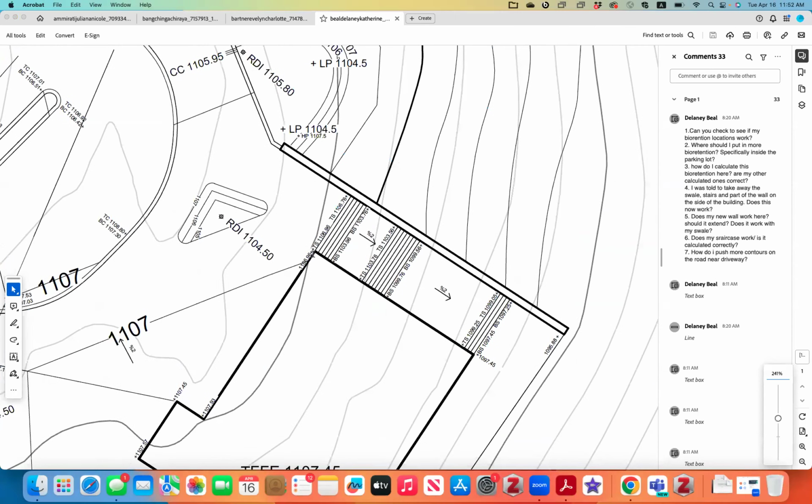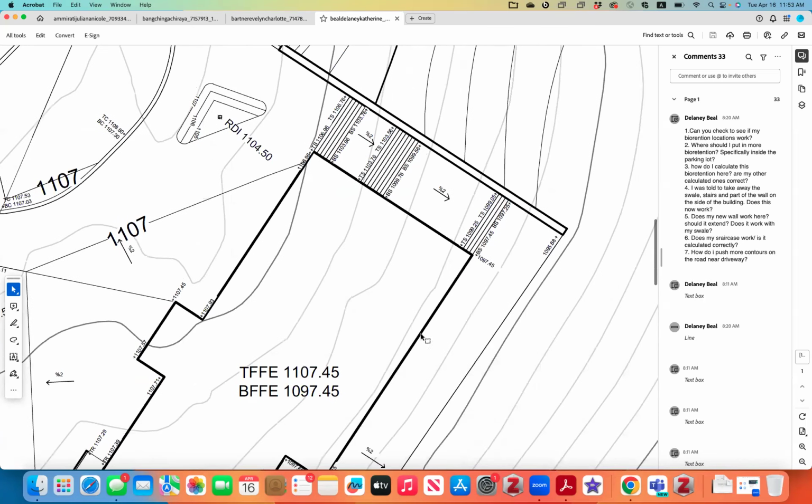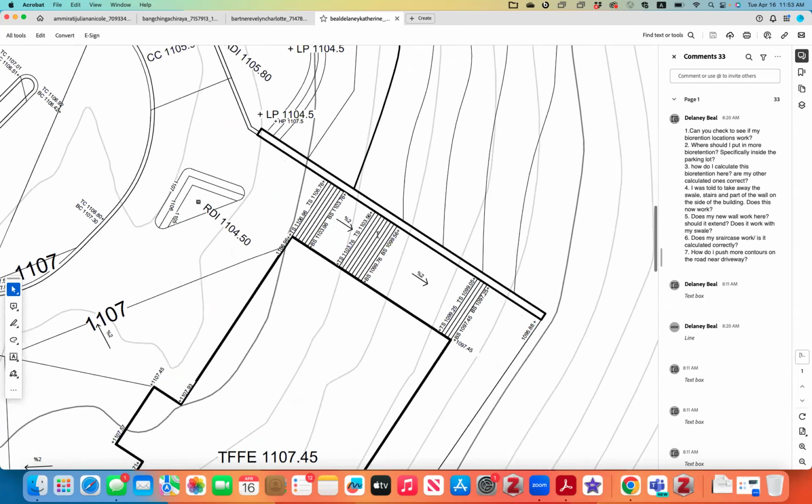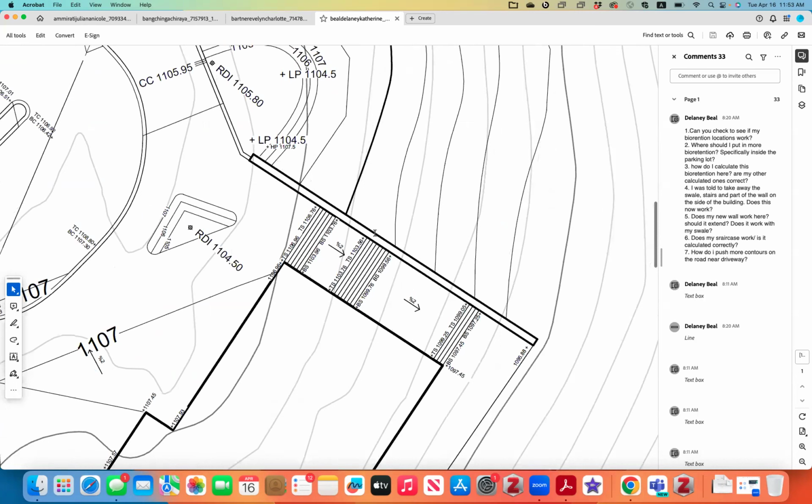So this one, the TS was calculated correctly. And the bottom should stay here, that's right. And it looks reasonable. All these elevations, their connections, they look reasonable. You just need to label with how many risers at what dimension.